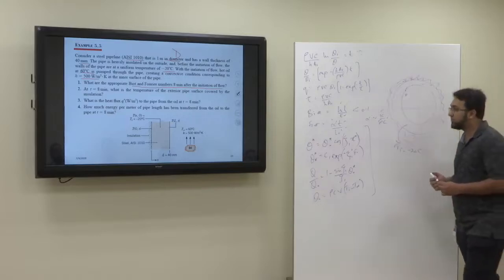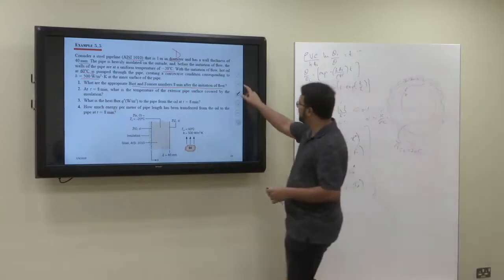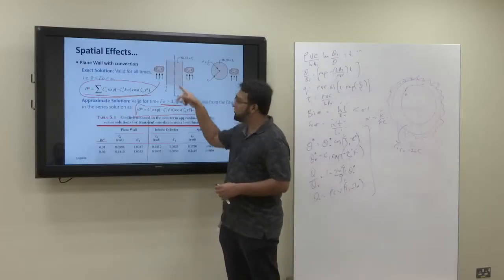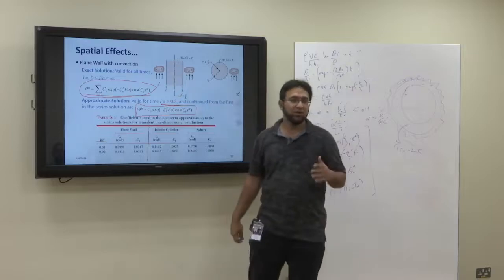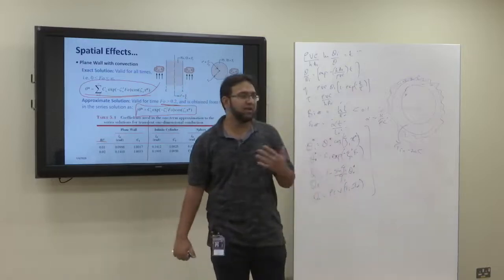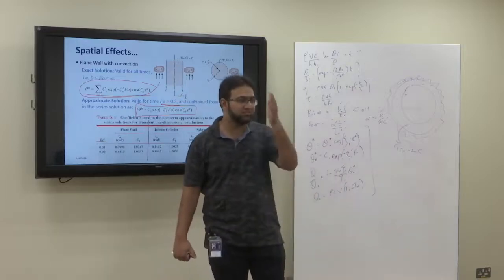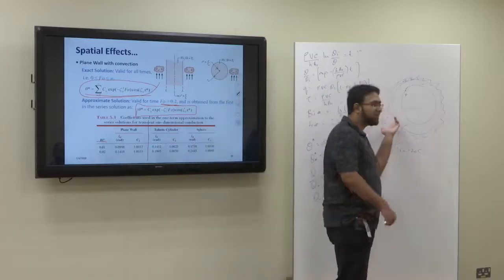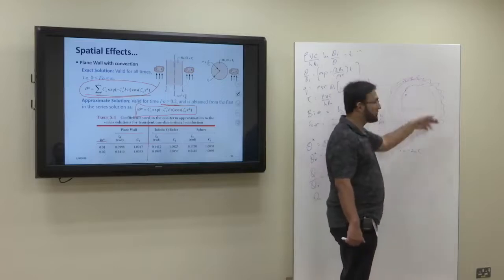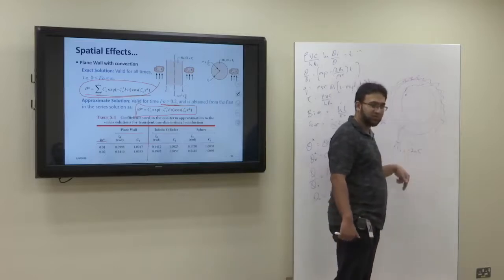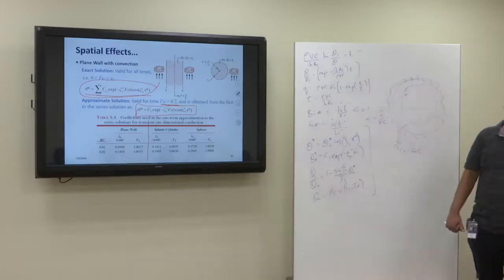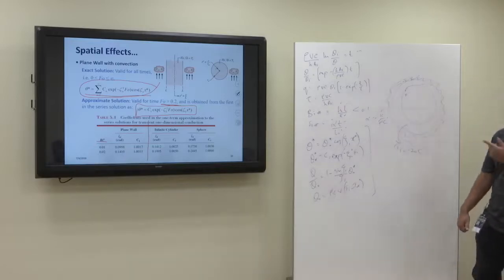Now remember, for this case we determined that there will be a surface where it's adiabatic, where we'll have the maximum temperature. In this case, the outer surface is the adiabatic surface where we have the maximum temperature because the insulation is applied. So that's the surface where the temperature gradient will be 0 for our case here.